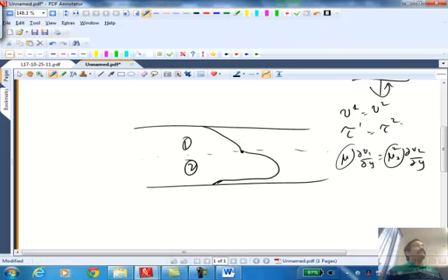That means that the velocity gradient doesn't have to be continuous. So you cannot insist that the velocity field be smooth like this. There will be a discontinuity in the gradient of the velocity profile, because there is a discontinuity in the ratio of the viscosities. Okay, so this would be an acceptable profile. Why? Because the gradients are basically both in the same direction.